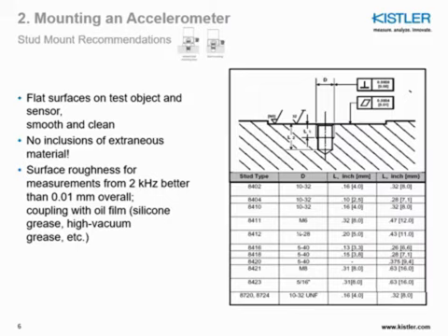First in line for the most rugged, stiff mounting you can do, the preferred method would be stud mounting. This is possible with sensors that have an integral stud or a thread to screw on a stud. We use that method to calibrate such sensors because that's where you get the best frequency response. When mounted with stud mounting, you can use a standard stud, or you could eventually use an isolated stud that has an integral plate in between the sensor and the mounting surface.